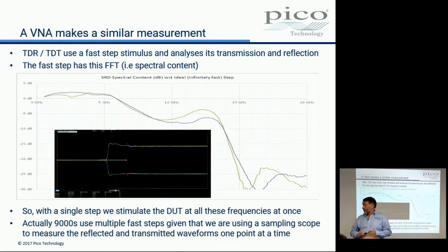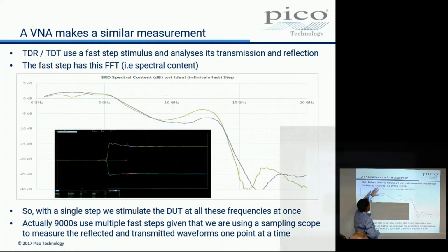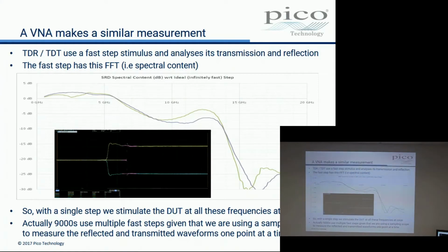Right, now a VNA. Yes, the VNA. Look, we're an hour in, and we're going to talk about the VNA. The VNA makes the same measurement, but in a different way. The TDR TDT uses a fast step stimulus and analyzes the response.